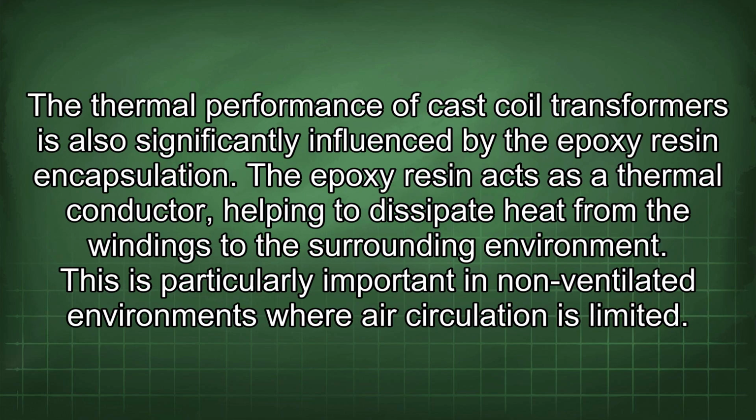The thermal performance of cast coil transformers is also significantly influenced by the epoxy resin encapsulation. The epoxy resin acts as a thermal conductor, helping to dissipate heat from the windings to the surrounding environment. This is particularly important in non-ventilated environments where air circulation is limited.